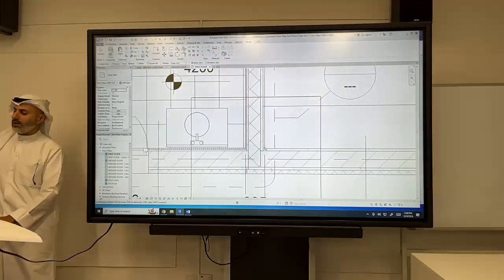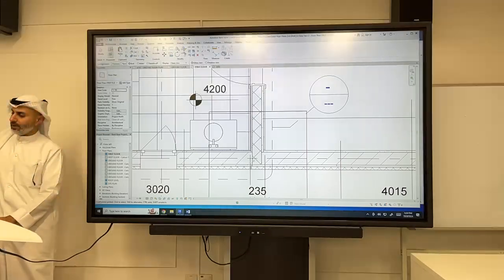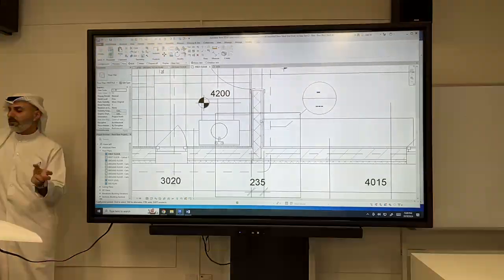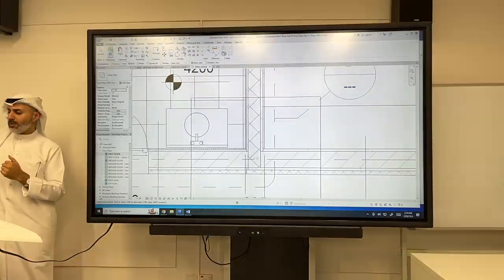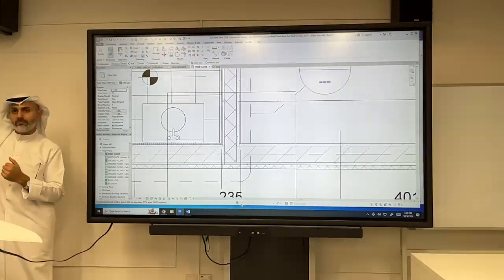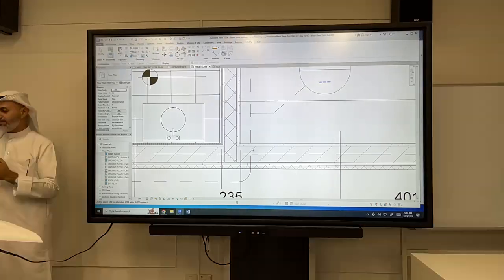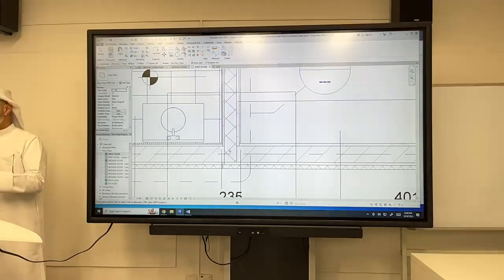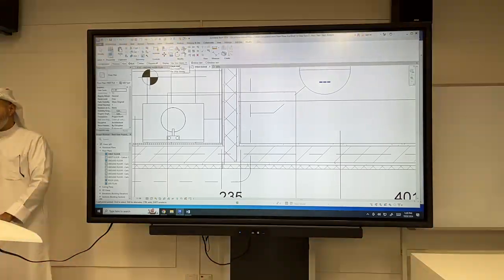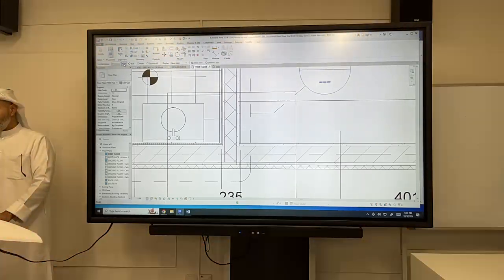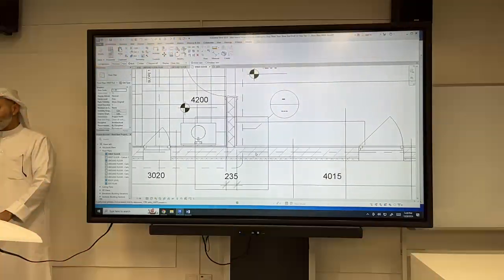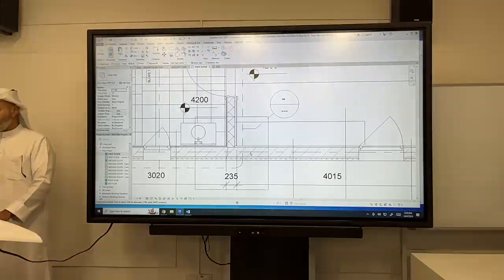So what's the connection that we want here? Now outside is white brick, right? Remember inside, I told you, since we don't need the insulation for temperature, inside should be black brick. So what's my ideal connection here? Should I let the black brick come out to the outside? This should continue, right? The brick under the white should be the one that continues. So you keep trying different options until you get to something like this. Once you're happy with this, you click once and you see the connection.